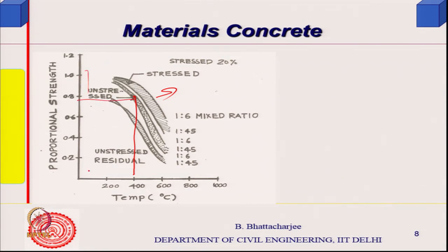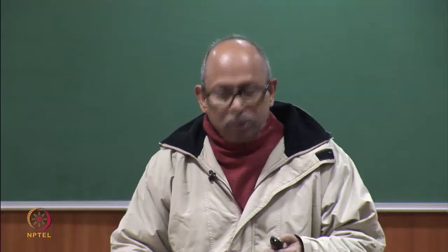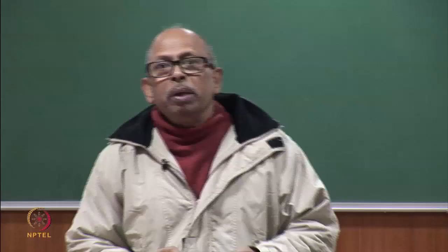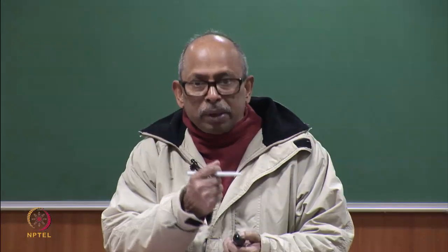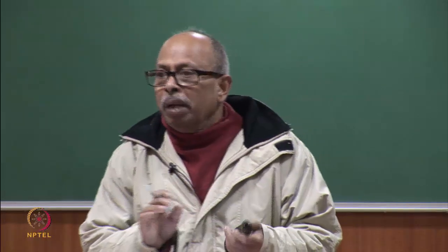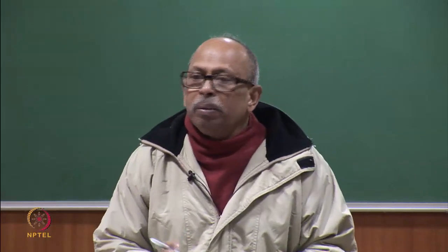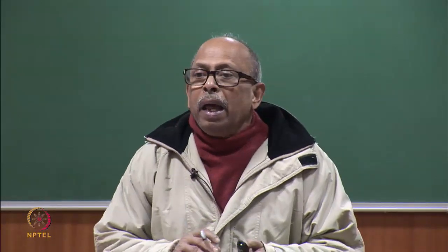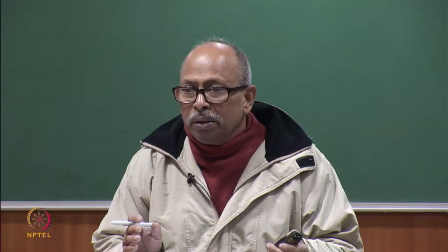Now, this is the relative strength being talked about. One stands for strength at ambient temperature, and this is unstressed residual. That means you have actually heated it up, cooled it down and then tested it. So, that is the lowest actually, because when you have stressed it particularly, it is under compression, because we are talking mostly in case of concrete or similar material, it will be under compression, and because of heating there will be some amount of expansion.